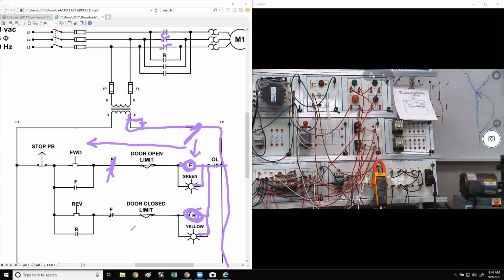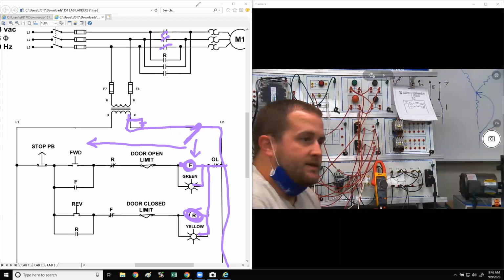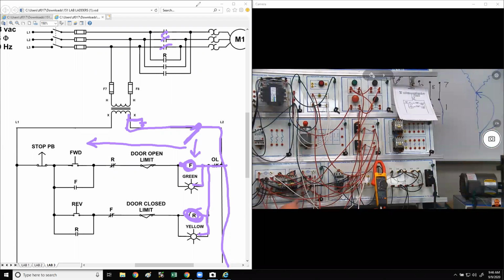So how can we verify that? I will ask you to double, triple check that this is the problem. I mean, obviously if we got 120 volts here and nothing here, how can we check to make sure that interlock is closed, or if it's working? Put it in reverse. Check the voltage. No.